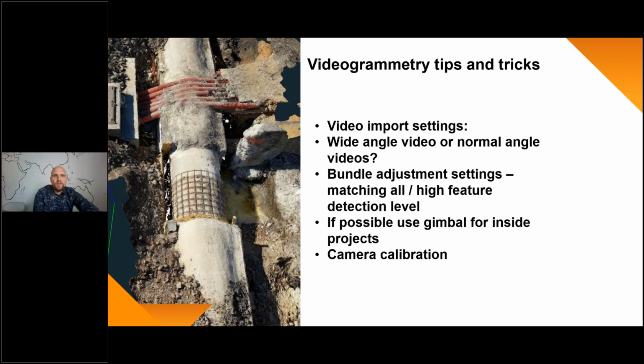So when recording videos to use with videogrammetry, first thing to consider is usually what kind of video settings to use. So most importantly here, we were wondering what will we get better results if we use wide angle video or normal angles, because on the newer phones you can select between wide angle, telephoto and different lenses. So usually the normal angle video camera will have best resolution, but for close range photogrammetry and videogrammetry, also wide angles offer some benefits. And actually in my example, the first example I did with wide angle camera and the second one I did with normal angle camera. Both of these work.